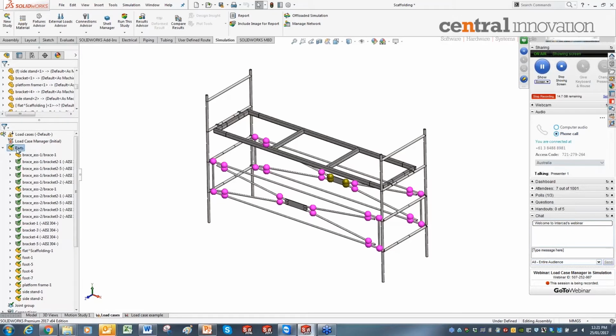or I can hold the parts folder, drag it and drop it onto the study 2. Just drop it on top of the study 2. It's loading now. As you can see here, my wooden plate is automatically excluded from the second setup, or the second simulation study. There is no wooden plate. And also, if you notice this parts folder, I have a green color tick mark, meaning all the material definition and the element definition is transferred from the previous setup to the new setup.